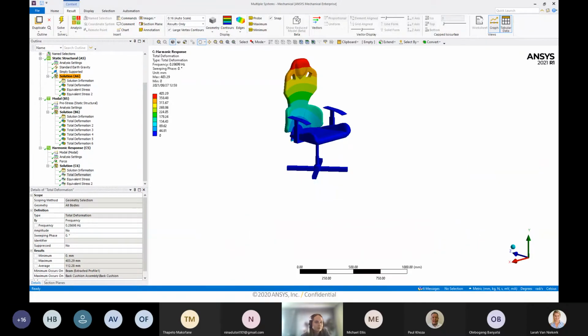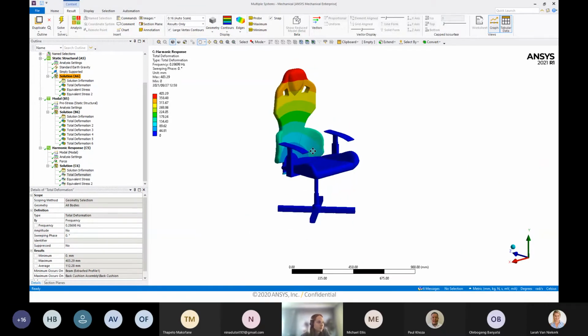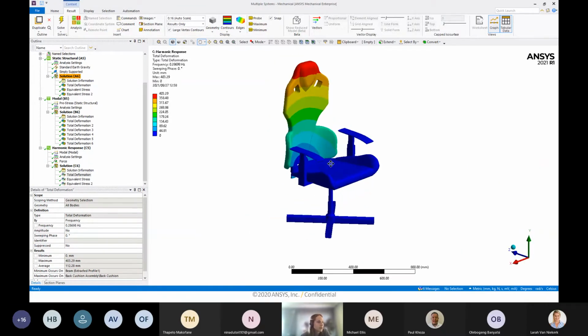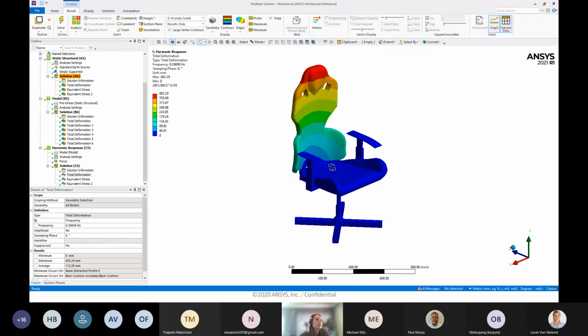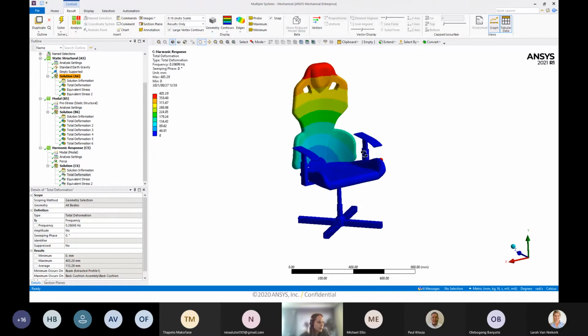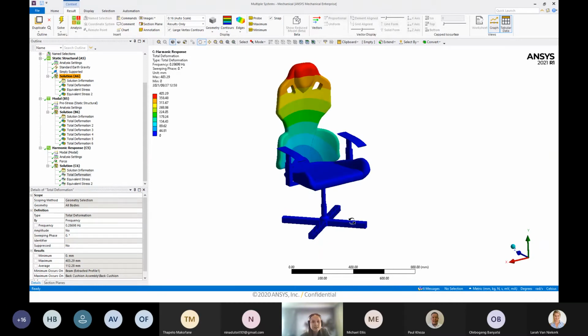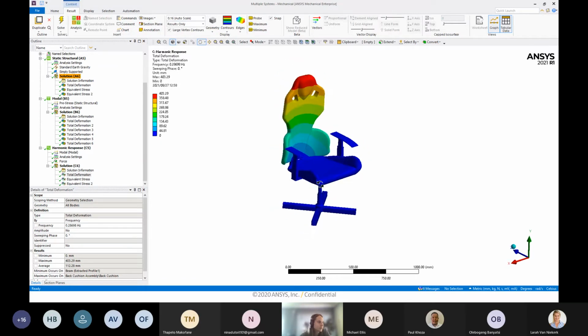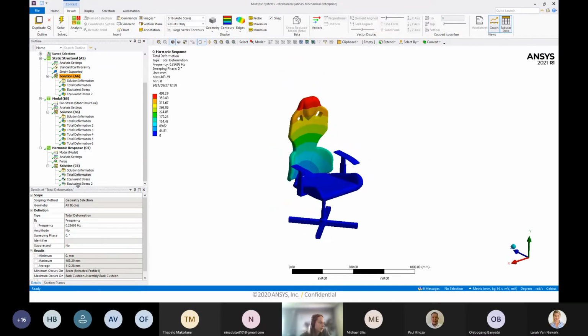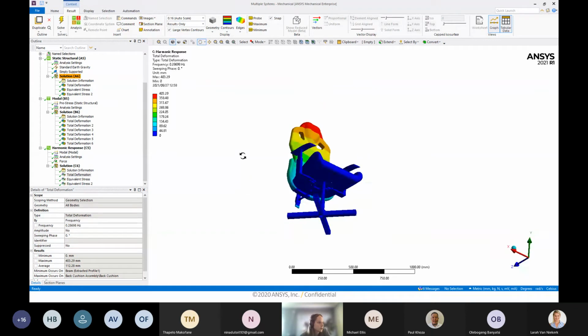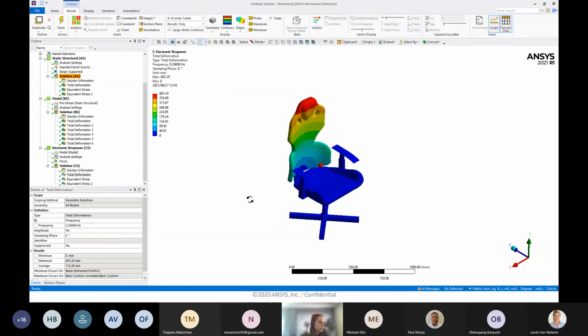So obviously that is excessively high, and this is probably due to the damping not being correctly applied. I don't have that information, unfortunately. So that's why doing analysis with damping included is a bit of a challenge. It's more a challenge to get that information, if that makes sense. But in this case, I did add a little bit of damping just to reduce the stresses. Before I did that, without damping, I think the stress at this frequency was something like 90 gigapascals or something ridiculous. So the harmonic response close to the natural frequency is excessive.